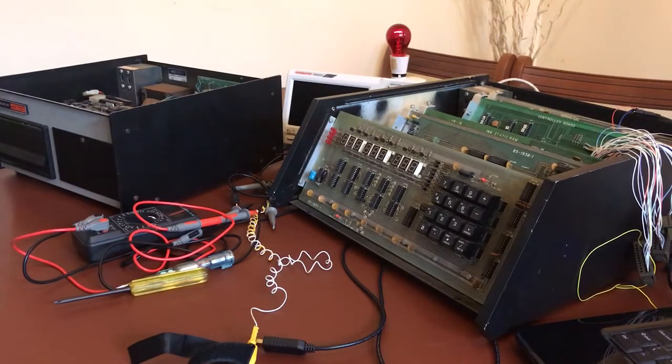Last night I made some more progress, not on camera, on the 16K RAM. I've managed to prove that it's two chips, two bits that are faulty. I think it may be more than one chip because there's two bits at each position. I was going to have a little investigate of that today.